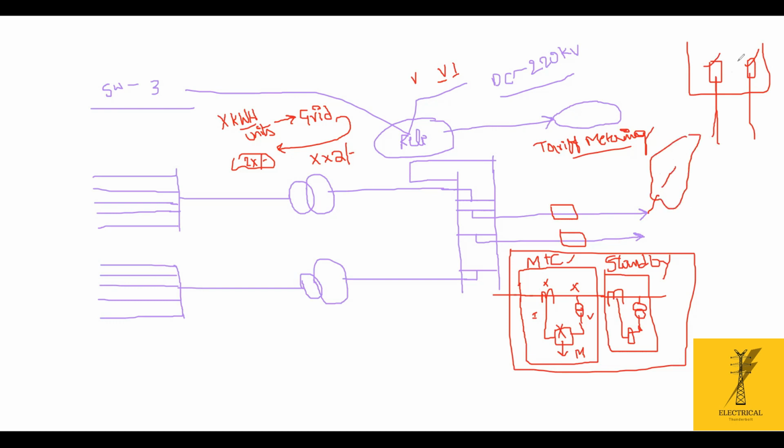If I am placing the meters here, the losses in the transmission line are borne by the grid person. In most cases, about 80%, the meters will be at the grid end. So who will bear the losses? No one, right? So the meters will always be in their position, unless it is project specific.